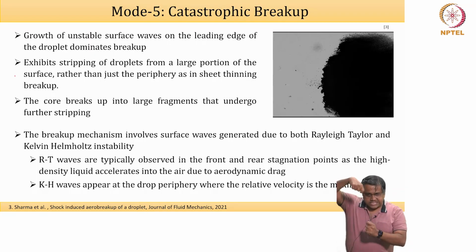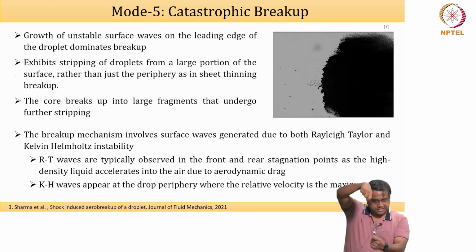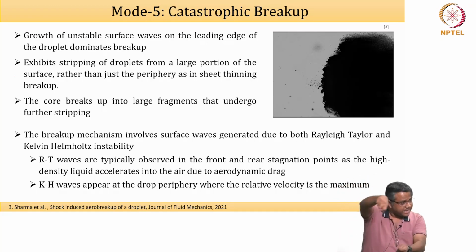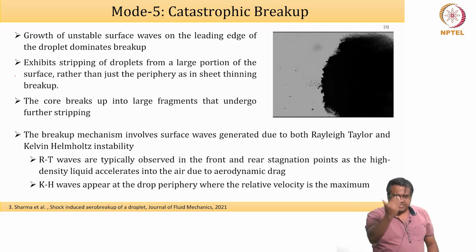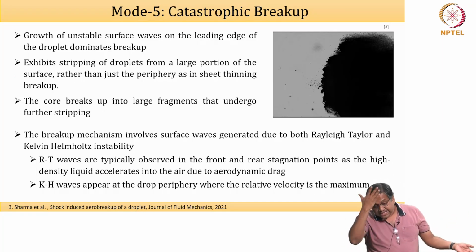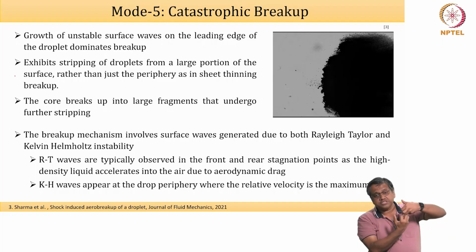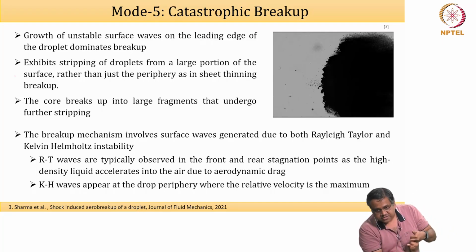If a liquid sheet quickly accelerates, remember it's a sheet, apart from the Rayleigh-Taylor instability it is supposed to also show the Darrieus-Landau instability. But unlike a flame, here you still have the surface tension to block the formation of the holes.